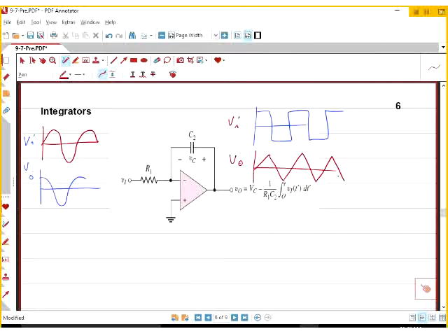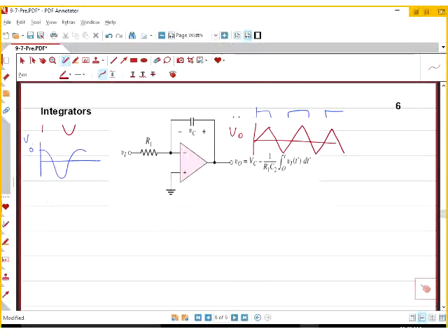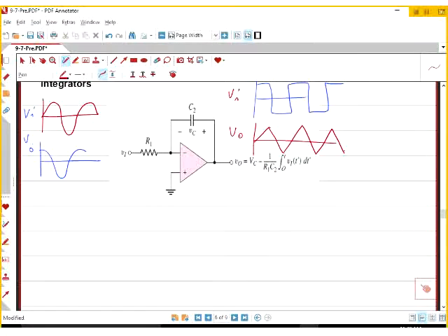That means integrator. It's also correct. It means you are integrating charges to get the current. Okay, for your project, what I'm expecting to see if your integrator works or not is if your input is a sine wave, your output should have a 90-degree phase shift. That means your integrator works correctly.